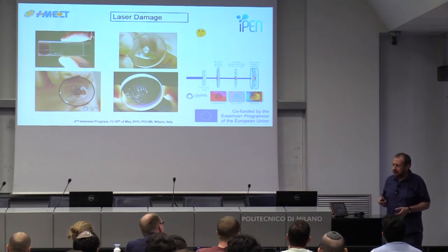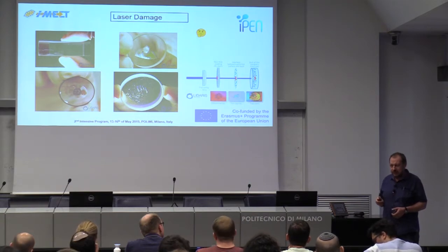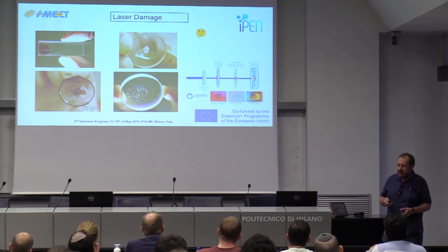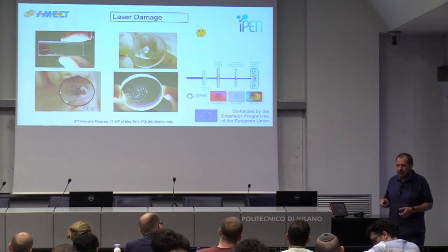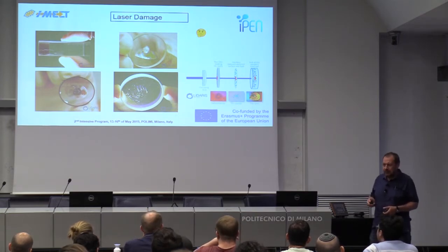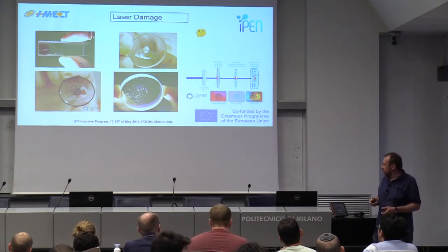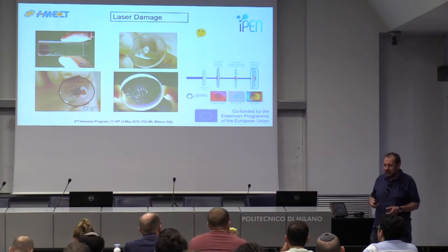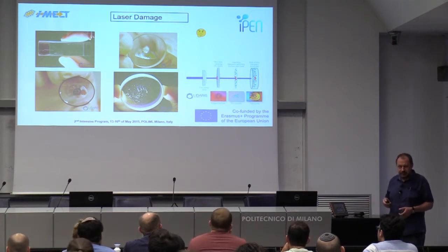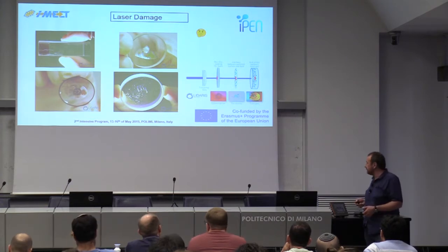And actually, it didn't happen very often, and it was not so dramatic, but it still made it clear to me that very different mechanisms are actually happening when laser interacts with a solid, depending on material properties, of course, the properties of laser pulse, wavelength, energy, and so on. And it also depends on the surface properties. Clean surface has a well-specified damage threshold. If you have dust on it or cracks, scratches, then the surface is damaged much more easily.